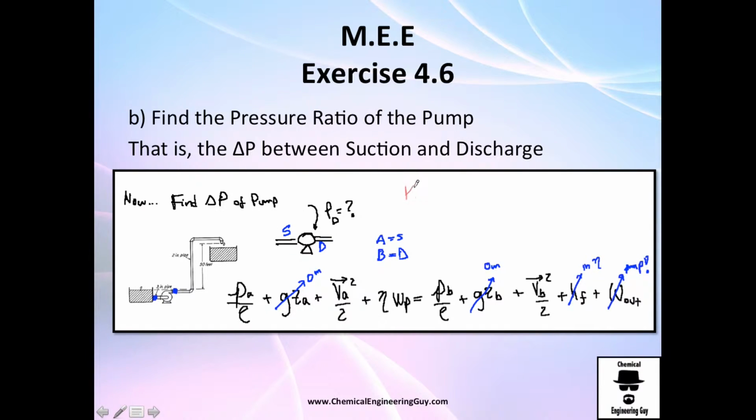Okay, remember that the mechanical energy equation can be applied at any point. We always choose this and this for convenience, but in this problem it will not make any sense to do that. We need to do a balance on the suction and a balance on the discharge, which are these points right here and right here. So the suction will be my new point A, and the discharge will be my new point B. Okay, actually it's right here, suction, discharge. Okay, let's do a balance right here.